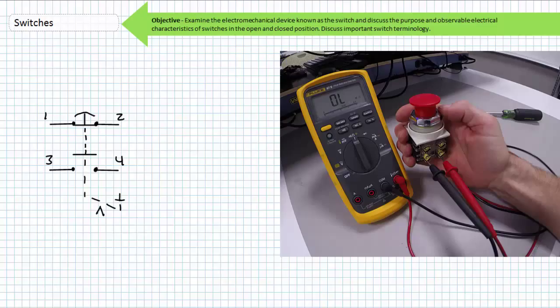Because they're placed in easily accessible locations for quick access in emergencies, the same convenient location means they're easy to accidentally bump. Sometimes emergency stops in high traffic areas employ guards that allow the button to be actuated in an emergency but prevent it from being bumped by a cart or your backside.